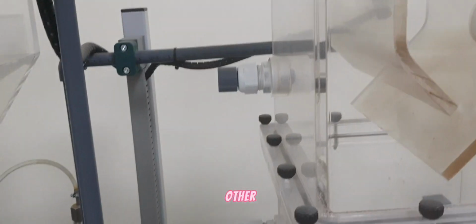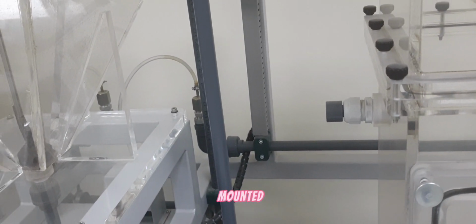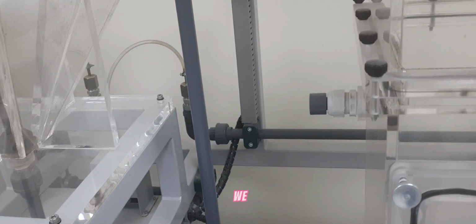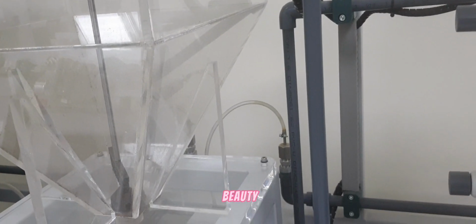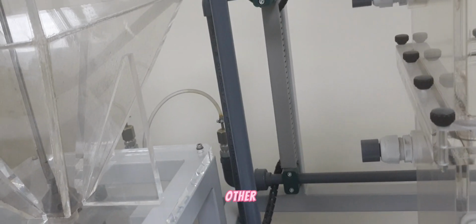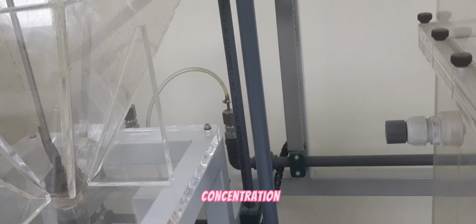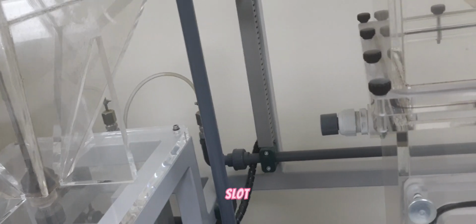It should not have water for long, so that the probes and the other things do not get corroded, and also remove the 2 pH sensors that are mounted in our device. So these are all things we have to take care of, and the basic thing is we can analyze the water which we are going to bring, the composition of the wastewater. Mainly we have to check the BOD, COD, and the pH, and the other parameters so that we can find out the biomass concentration, and the volumetric loading, the sludge loading, sludge age, and the return sludge ratio.